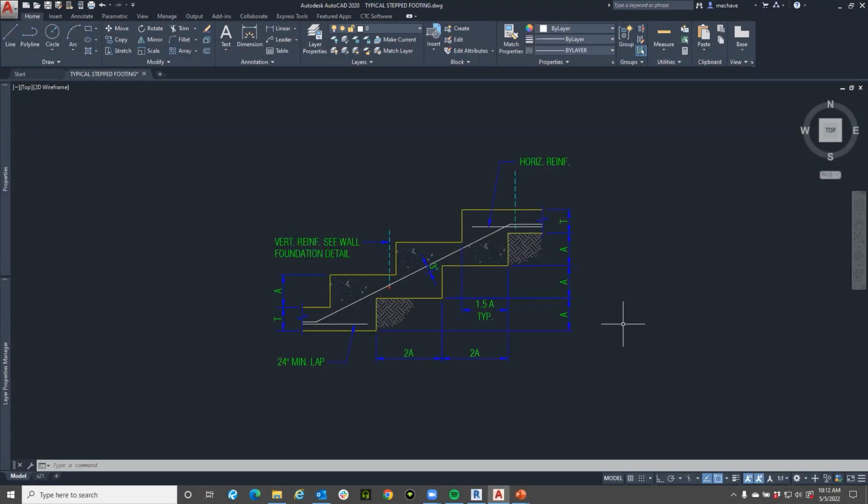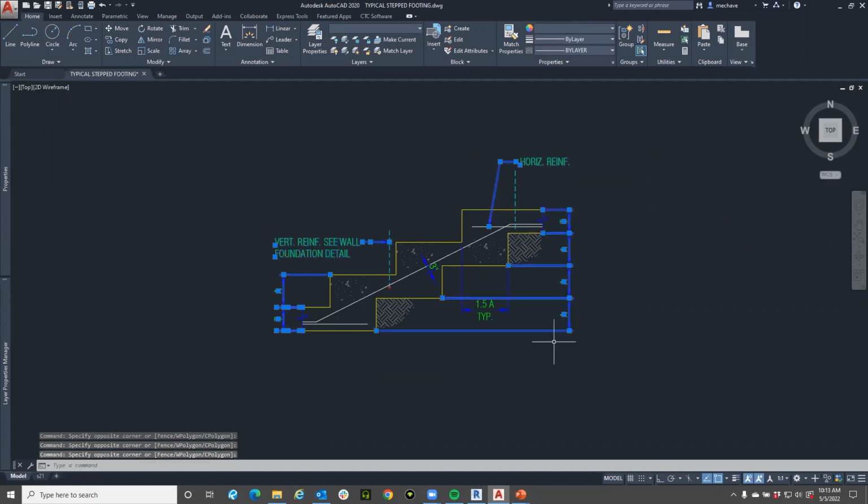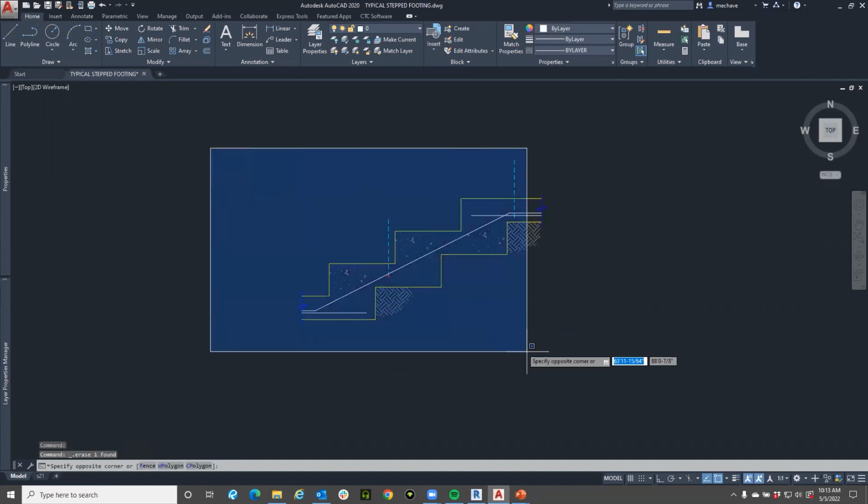This is the only one I've modified from my files, but what you can go through and do, and now this is your judgment call, if you want to figure out your hatch patterns, by all means, keep your hatch patterns in here. But I personally do not bring in anything but my line data. So I'm going to delete everything that is not going to be dimensions, and it's not going to be any of my text items for these ones, okay? All it's going to be is my line data.